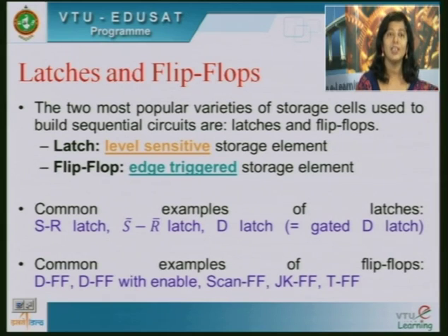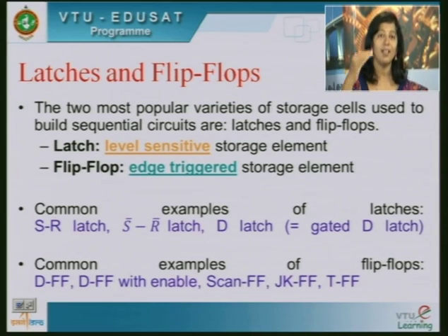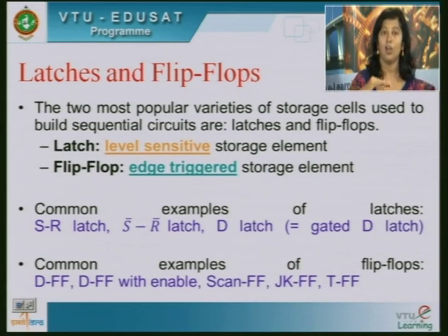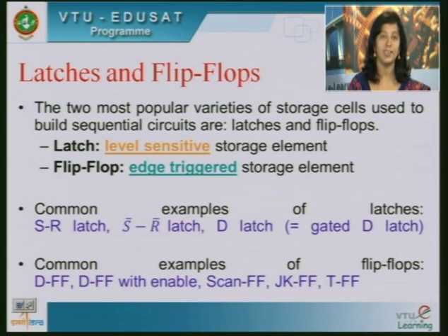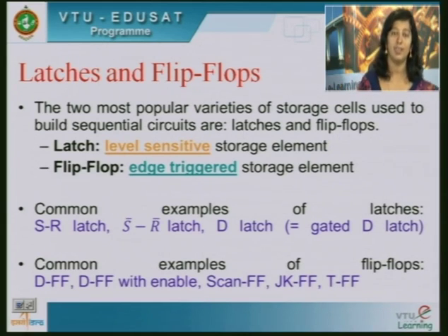A latch is nothing but a level sensitive storage element. That is, it senses a level, either a high or a low. It detects the levels and works according to levels, whereas the flip-flop is an edge triggered storage element. Usually the clock edges which I spoke of in the previous slide, positive or negative edge, that detects the change, it's a flip-flop.